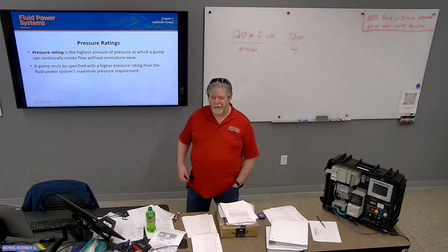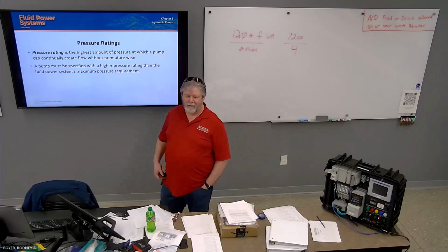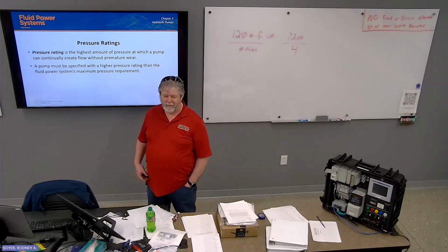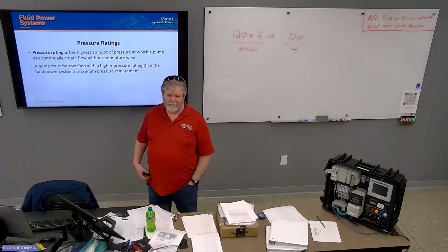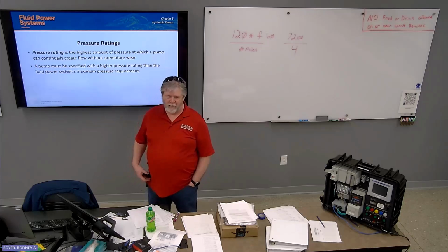So basically you'd want a high enough pressure rating to handle all of the pressure requirement of the system as well as any overpressure in the system, if there is any. Okay, but why? I think it would help prevent the pipes busting. That's why you put pressure relief in the system. Does it protect the equipment? Protects the pump.